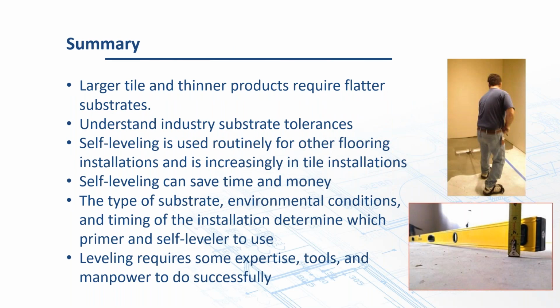In summary, larger and bigger tiles, thinner materials as well, require flatter substrates. Understand the industry surface substrate tolerances. Very, very important. Again, if you meet those tolerances, your installation should go 100% better, much easier, much faster, more productive. As I said, they've been used in other floor coverings forever. Now they're just going to become more common in tile because of the size and format of tile.